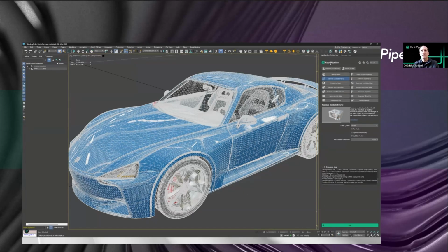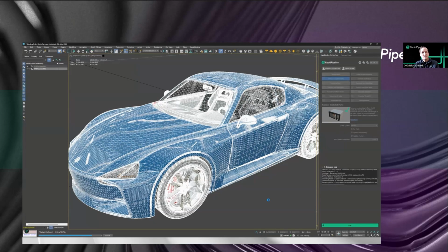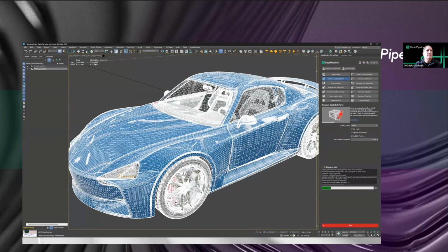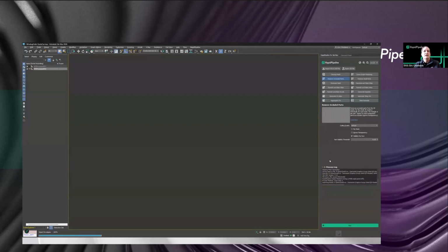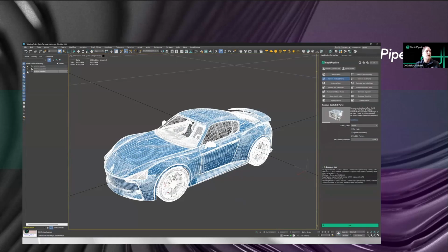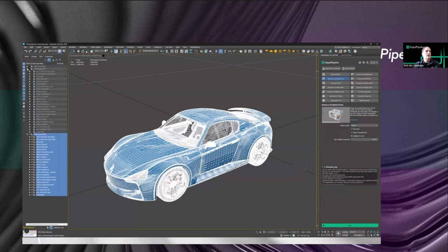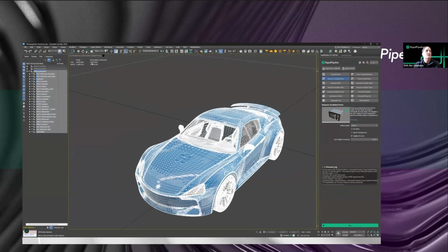And I'm going to go ahead and run this. Now it's going to look at the whole model, all the parts, and we can see the original resolution is 2.986 million triangles. What it's doing is computing the triangle visibility for all the meshes. Then it's going to skip decimation because we told it I don't want to do any decimation, I just want to do this culling. It finishes, pulls it in and hides the original file in the scene, and shows us it's now at 2.895 million.